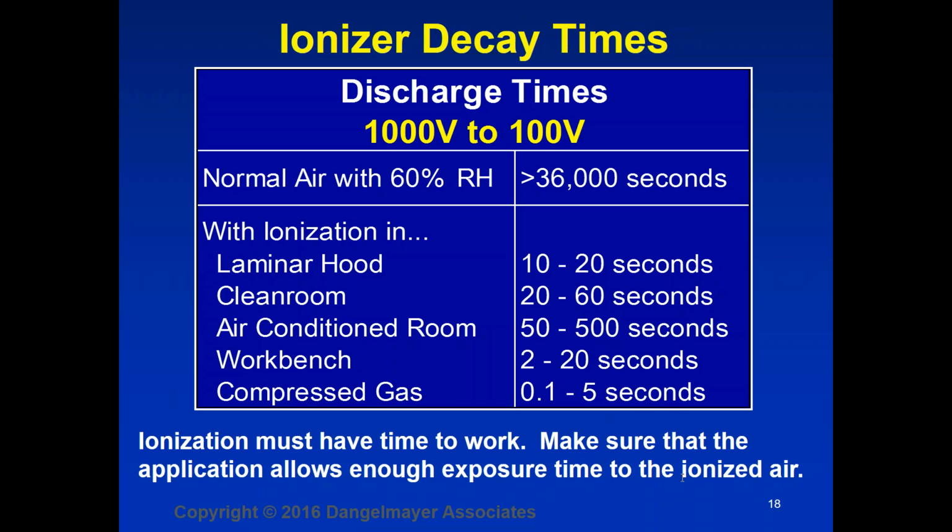Excuse me. Arnie, yeah, go ahead. Really good question. How does humidity remove charge? Well, what humidity does is put a layer of moisture on the surface. And this layer of moisture gives you a somewhat conductive path to ground. So if objects are coated with this layer of moisture, eventually the charge will bleed off, but it's really not a low resistance path. It's a very high resistance path, and it takes a very long time for that charge to go away.